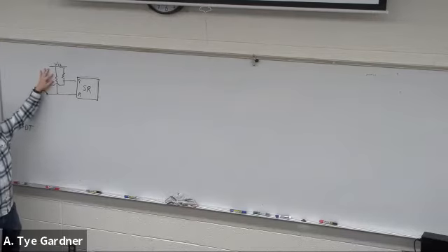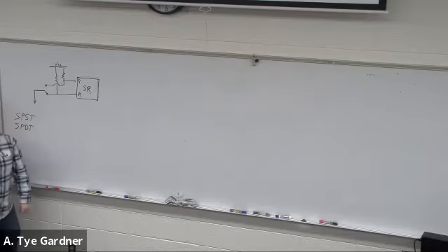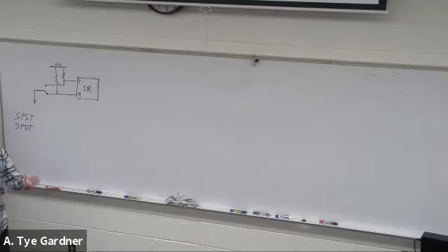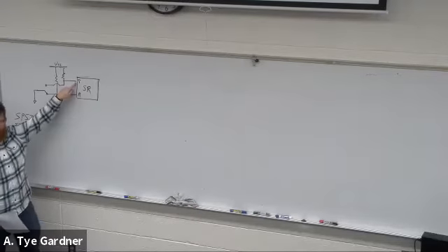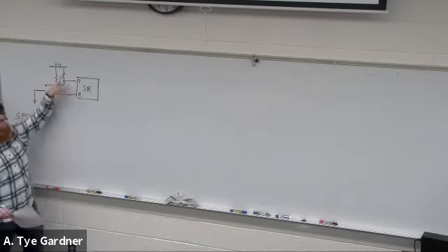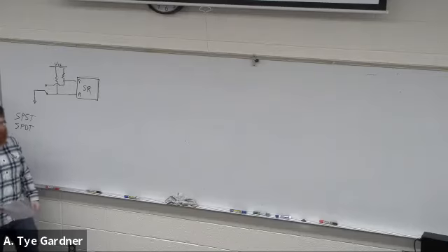And the other nice thing is, because they can be big, these can actually be transistors, because you can use a transistor as a resistor. So it can still be small, because small means big resistance. And since we're talking about human inputs still at this point, they can be very big because the time scales don't really matter. Humans are super slow compared to a 400 megahertz clock. So any capacitance at this input plus a big resistance is going to make a nice slow characteristic.